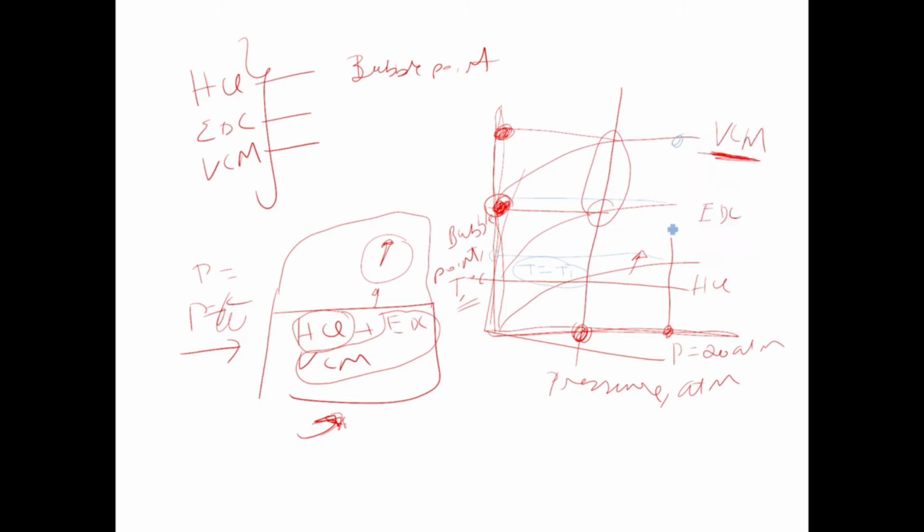So when we use distillation, we take our fluid mixture and maintain this particular pressure and some temperature within this range, so that you can collect your hydrochloric acid, and the remaining two components will stay at the bottom as heavier components. Because these are less volatile, and your hydrochloric acid is more volatile. So we have to generate this type of graph. Aspen HYSYS can do that, and that's what I'm going to show you before we design the distillation column.